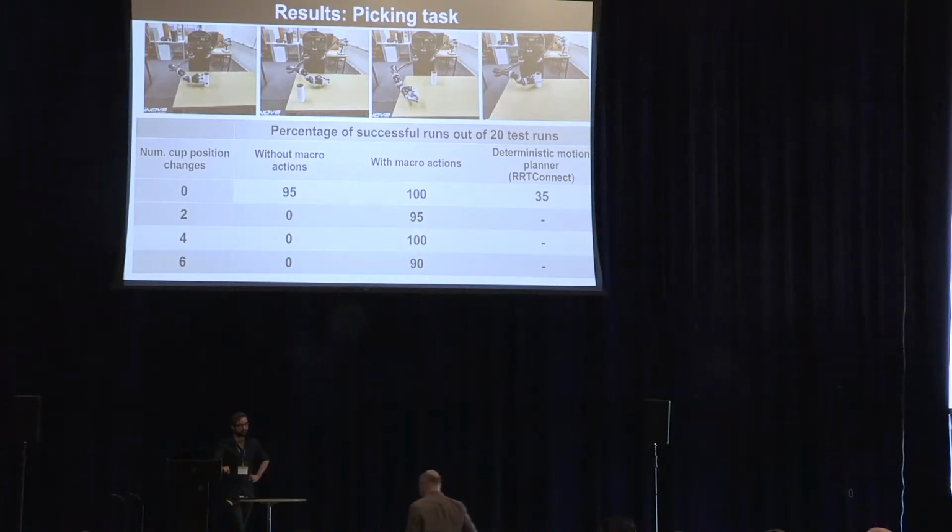A couple of questions. One would be, how do you discretize the continuous variables in your state space? Our state space is continuous. As I mentioned before, we have a hybrid space, which consists of several components, where the first component is the joint angles, which operates in a continuous space. The other variables, the gripper state and grasp state, are discrete states. So we have a continuous state space, continuous observation space, but a discrete action space, because at the moment, solving POMDPs with continuous action spaces is still very early research. So we decided to keep the action set discrete.